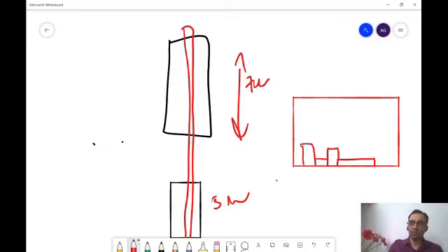So what is done is, we say that, okay, nothing of this sort. All the cells that you have to make, whether it is an inverter, a NAND gate, a NOR gate or an AOI or whatever cells you are making, we will use a standard fixed height. Now what you can change is that if there is a small cell, you will use only this much width. But if it's a big cell, you will use much larger width. The height is fixed.